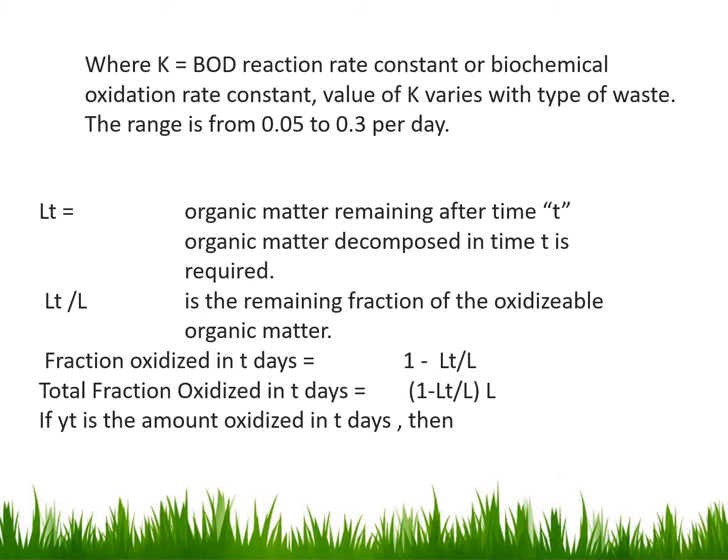If we subtract this ratio from 1, it will give us the amount oxidized, the fraction oxidized in time t. Now the total amount oxidized in t days is obtained by multiplying this fraction by the total amount of organic content, L.